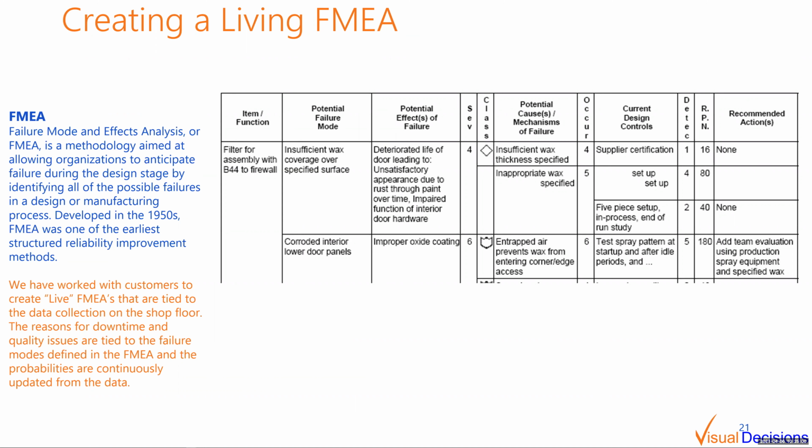what is the actual cause of the failures and so forth, you can actually track what is the severity, what is the probability of occurrence, and identify what is your probability of detection by utilizing these as how you capture information on the shop floor. And if you tie the way that you're capturing the data on the shop floor into this process FMEA, you can automatically set your severity, your probability of occurrence, and so forth.